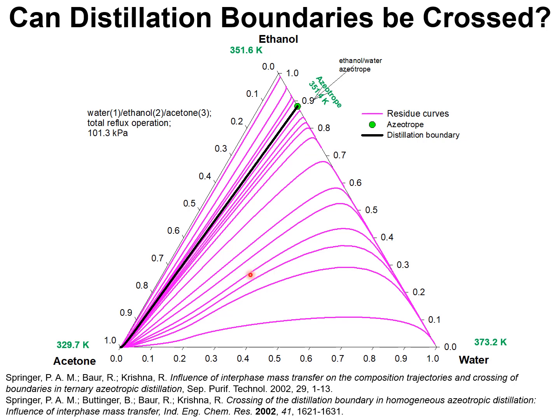Put another way, if we follow the concept of theoretical stages and residue curve maps, a distillation column with feed mixture anywhere here cannot be distilled to produce pure ethanol. That is only possible to produce pure ethanol if we have feed mixtures with compositions on the left of the distillation boundary.